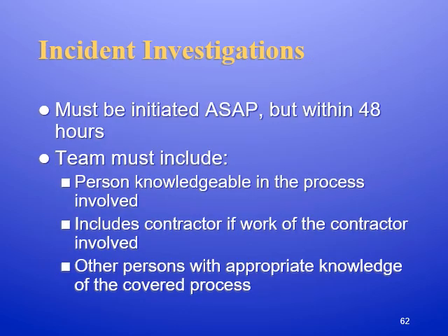Incident investigations must be initiated as soon as possible, but within at least 48 hours. The team must include a person knowledgeable in the process involved, includes a contractor if work of the contractor is involved, and includes other persons with appropriate knowledge of the covered process.